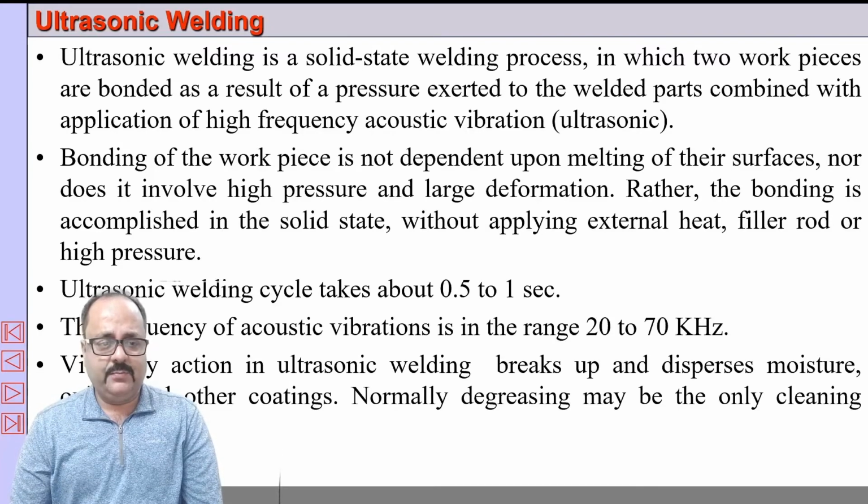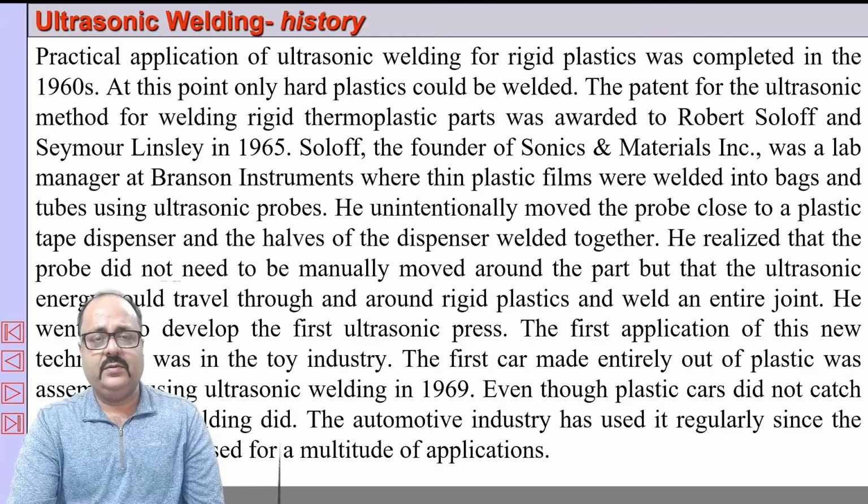Now here one important thing is the vibratory action of the ultrasonic welding breaks up and disperses the moisture, oxides, and any other coatings that are there, and normally only degreasing may be required for cleaning.